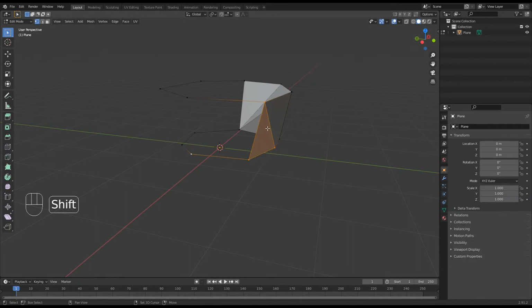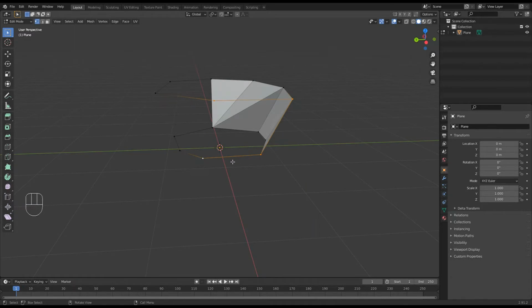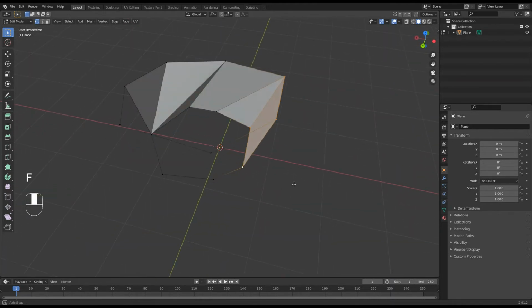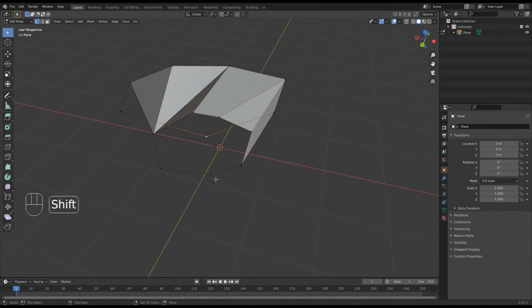And if I continued, you'd end up with 2 faces on top of each other. So when you are doing this sort of filling, you must make sure that only the surfaces, or the points where you want to build a surface, are selected. Okay, I think this one could also be a quad. It doesn't seem to be bent too much either. It isn't selected at the bottom.